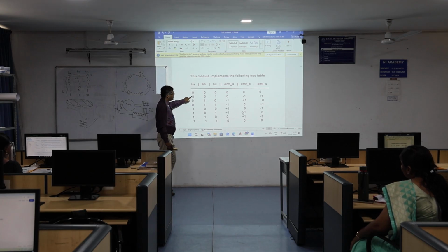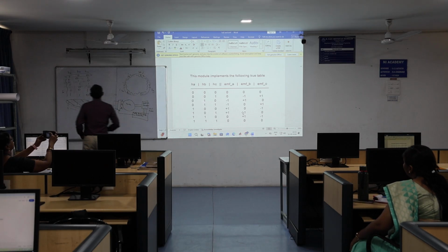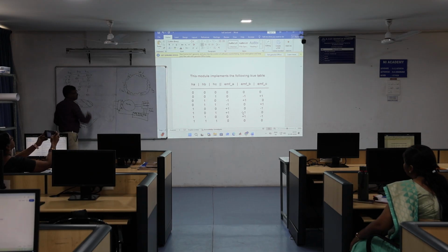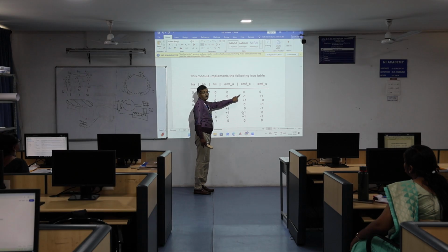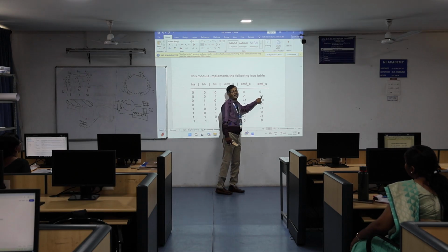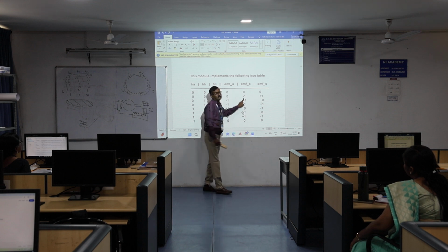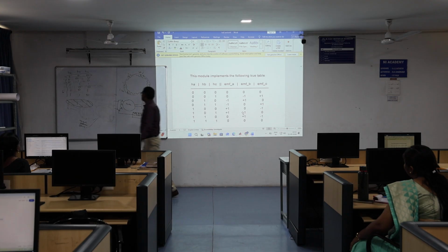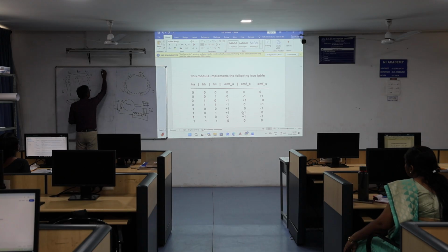State number 1 is 0, 0, 1. State number 2 is 0, 1, 0. And when HC becomes 1, your EMF is generated in 2 windings: B phase winding and C phase winding. C phase gets a positive pulse and B phase gets a negative pulse. So what we have to do: after reading your Hall sensor, EMF will be created.